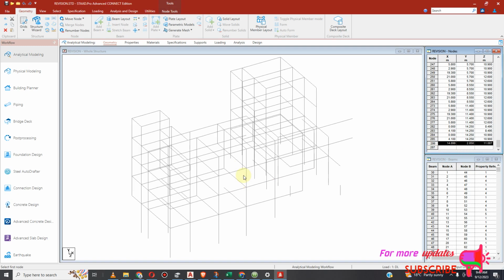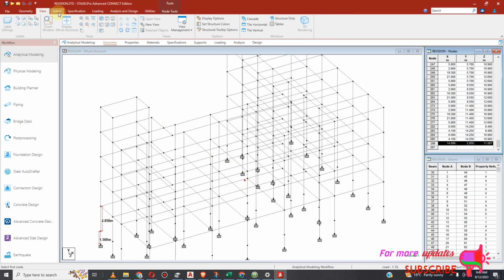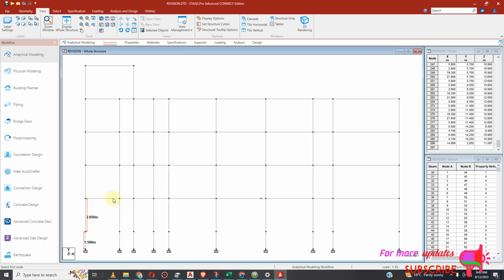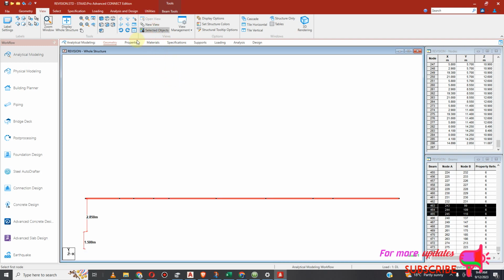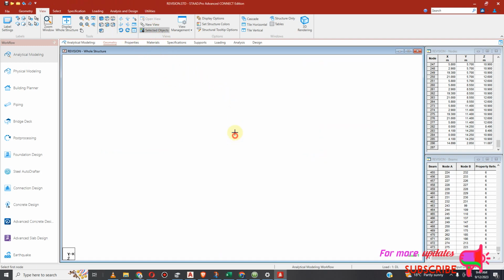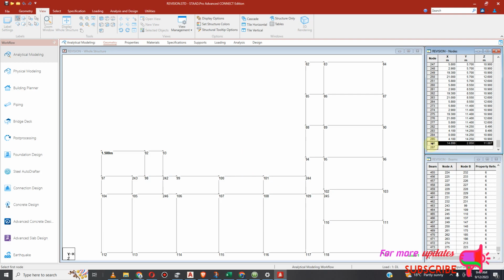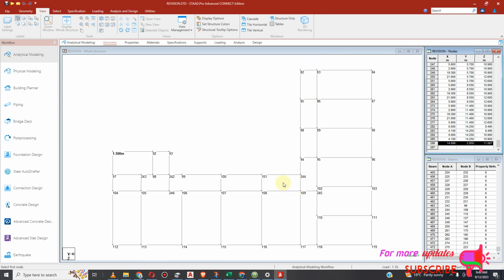You can see the one marked in red here. So if we go to side view, and then we select this, and then view selected only, and then go to plan view, and then Shift N to display the nodes, and then select our node.